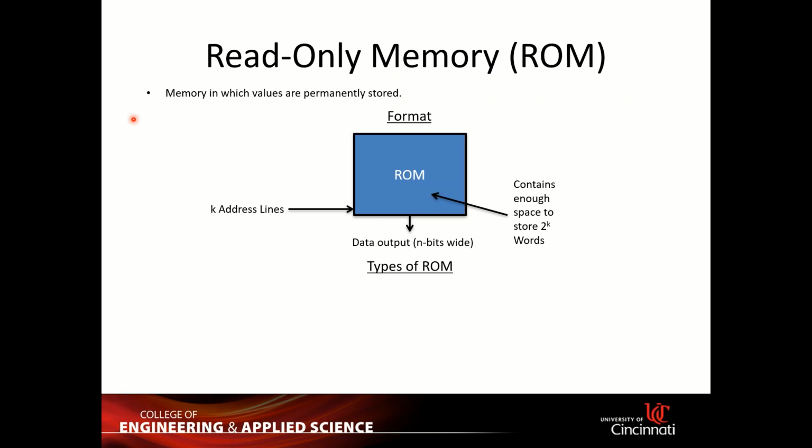If you design some program, you can send your truth table to the manufacturer, and the manufacturer will convert that truth table into a design for your certain computer output. Then the manufacturer will make the mask corresponding to whatever 0 or 1 that you want to put in your truth table. Then the mask will physically store that program information into the device.